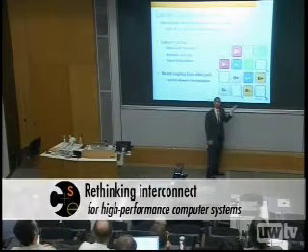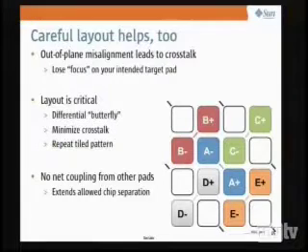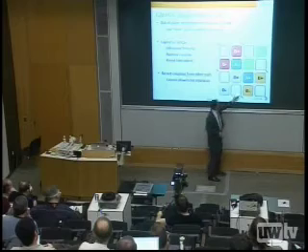So imagine A and A bar are my bits I'm trying to communicate. And if I separate the two chips, inadvertently perhaps, trying to see A bar, I may actually see B and B bar also. But because they're arranged in such a way that they're equally contributing to noise, they have no net effect on my communication. Similarly for E and E bar.